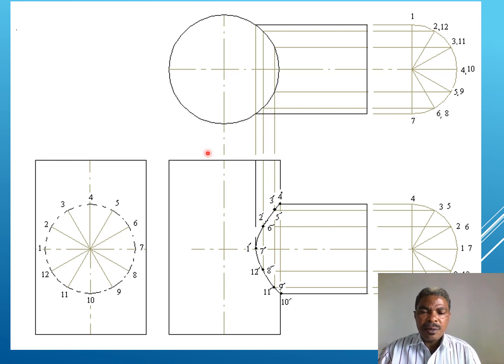So how do we obtain the curves by construction on sketches or drawings? We need to use the dimensions provided in our case. We have to first draw the plan view for our two cylinders intersecting, interpenetrating. As you can see, this is the standing cylinder and this is the one in horizontal interpenetrating the standing cylinder. It's very important to draw the end view of it,